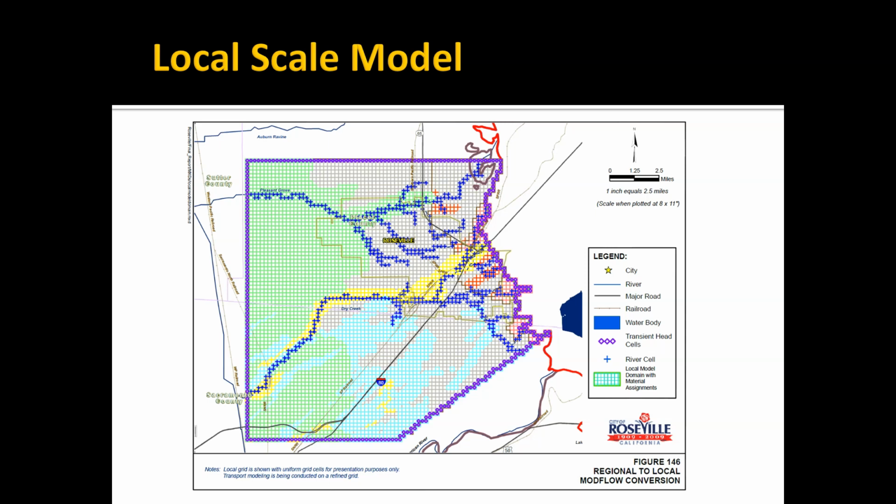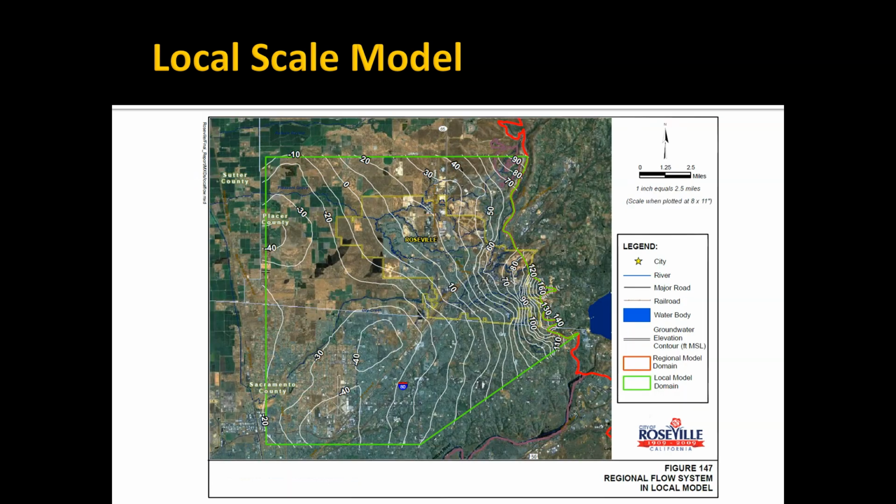And in one case, they had a landfill where there was a fire burning underneath it, and they wanted to do some groundwater analysis around this crazy landfill that they'd been dealing with for a while. So basically, we just created this local scale model inside the regional model and extracted the boundary conditions from the regional model, extracted the hydraulic conductivities and the recharge, and then we were able to run this local scale model independent of the regional model.